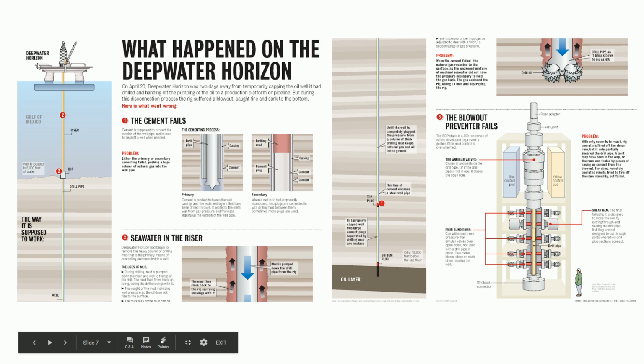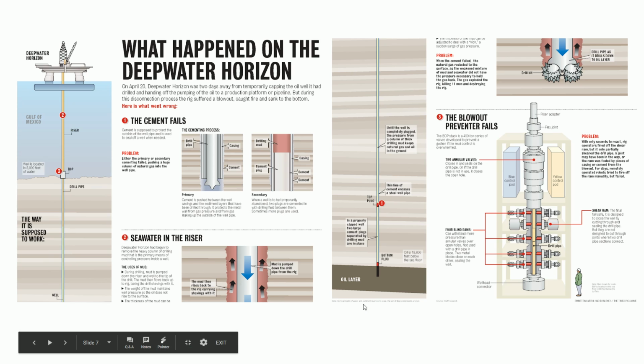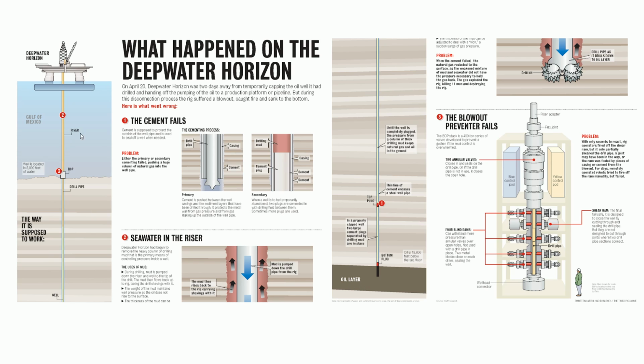All right, so here's Deepwater Horizon. There's the BOP, 5,000 feet below the surface, and then the well goes down for another 18,000 feet. Some of you might know from your engineering courses, but in order to build these kinds of pipes, you have a drill, and the drill goes down, and then once the drill goes down a little bit, you fill up the well behind it with cement to stabilize the sides, and then you can push the drill bit even further. So you're constantly trying to build a little pipe, a little tunnel for you to continue drilling through.